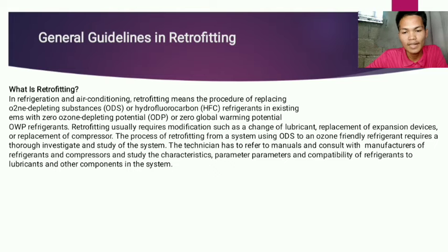Retrofitting usually requires modifications such as change of lubricant, replacement of expansion device, or replacement of compressor.